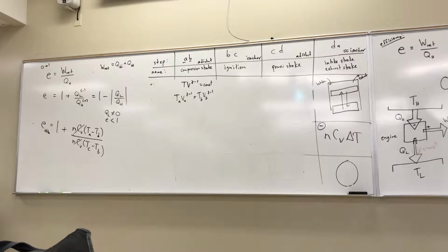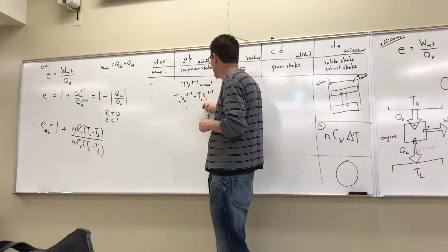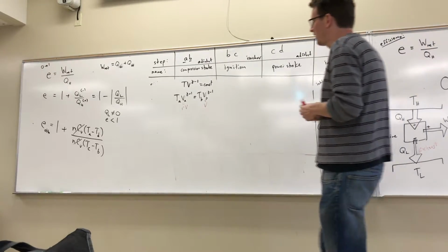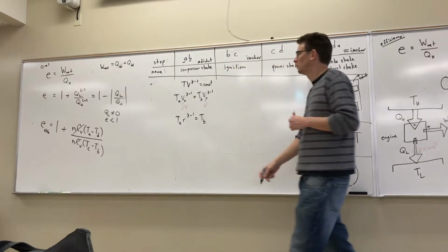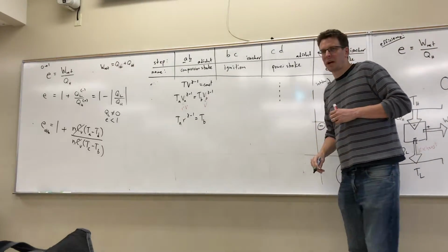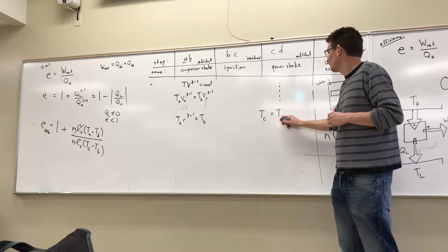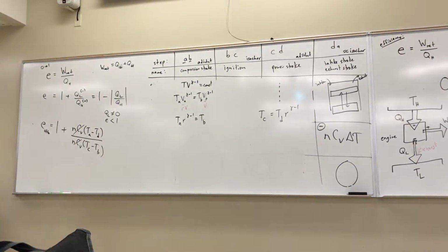Is that okay? Now the volume V_A is RV, and the volume at B I just call V. Remember, that was the way that I characterized those temperature extremes. So this tells me, if I cancel off the common stuff, that temperatures A and B are related in this way. Same idea over here on the power stroke. This will be T_C, and this will be T_D. The only difference is that the R term is on the other side, because now I'm going to higher volume, and so higher volume is the final.